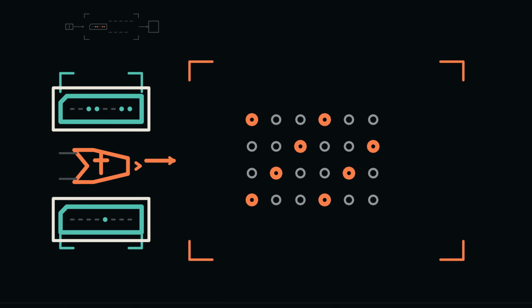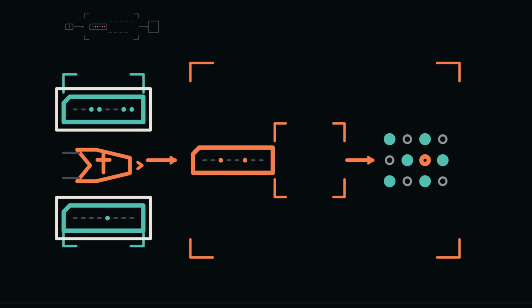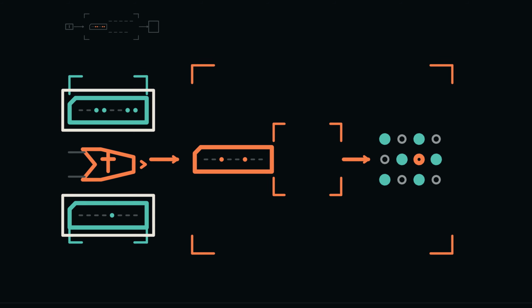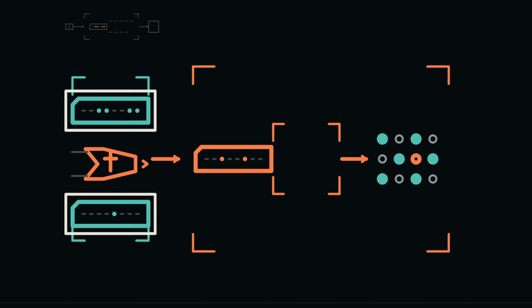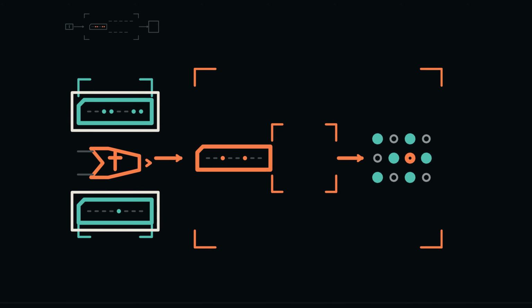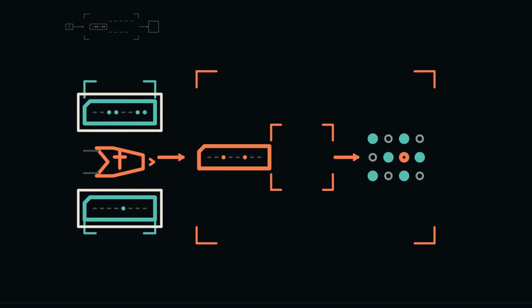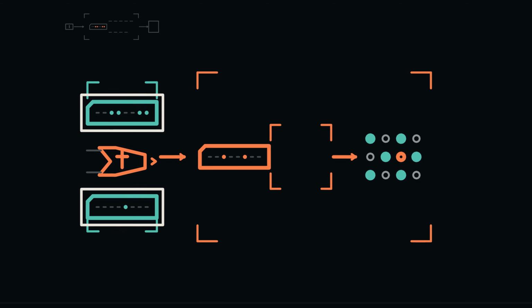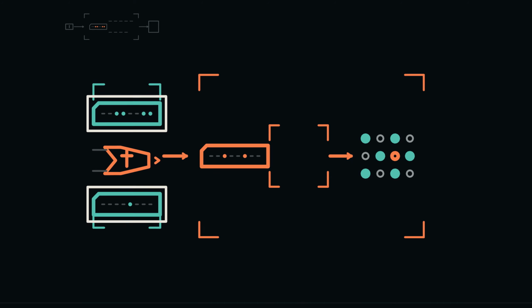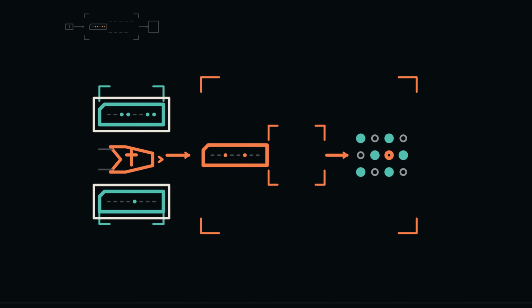A modern solid-state drive also preserves a simpler outer contract while changing its interior. The host submits reads and writes for logical blocks. Inside, a controller maps those blocks onto flash locations, corrects some errors, moves data as cells wear, collects still valid data before erasing larger blocks, and may keep several commands in flight. A logical block number is not a permanent physical cell address. The controller maintains the mapping that lets the outer storage interface remain stable while the physical placement changes.